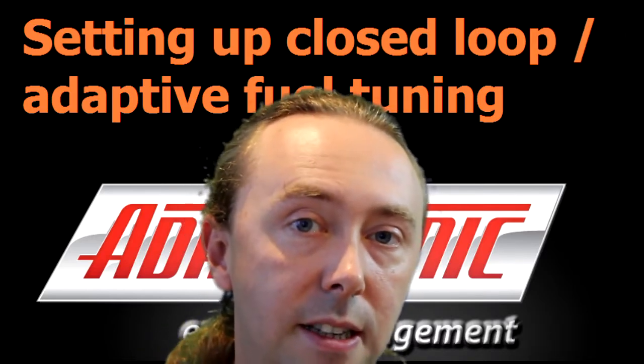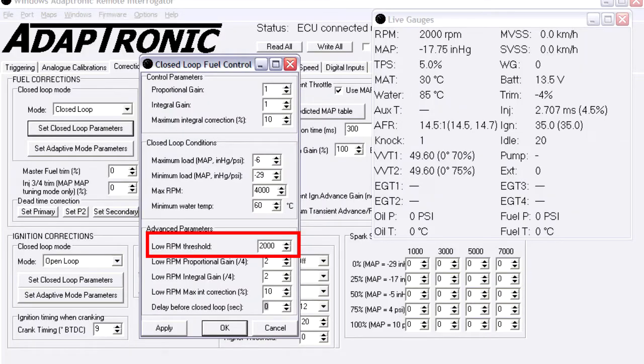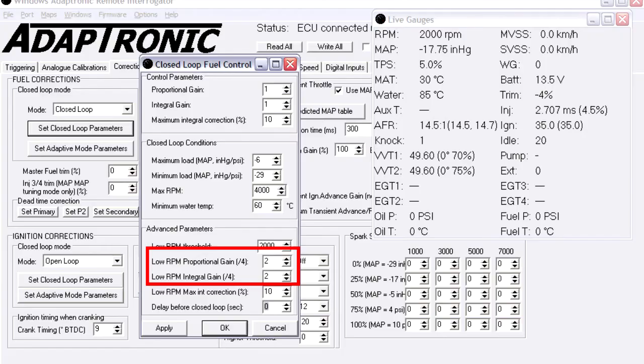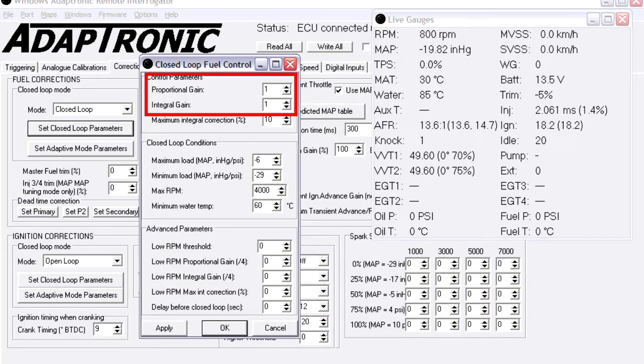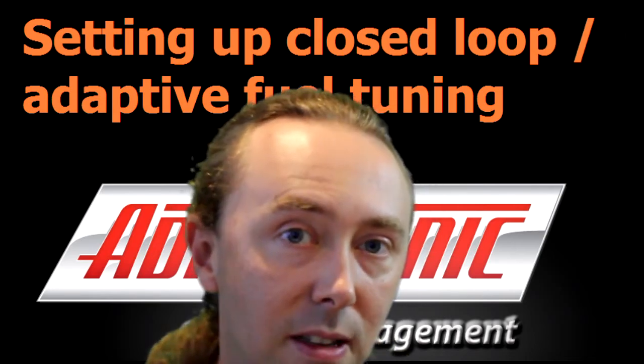You can also tell the ECU to use lower proportional and integral gain values at lower RPM. In particular, this is useful on engines where the transport delay is quite large at idle. To set this up, you set this RPM threshold to be a non-zero value. Then whenever the RPM is less than that, the ECU will look at these settings instead of those ones. The proportional integral gains in this section are 1/4 the sensitivity of these ones. So to replicate a gain of 1 in the normal settings, you need to put 4 into the low RPM settings.